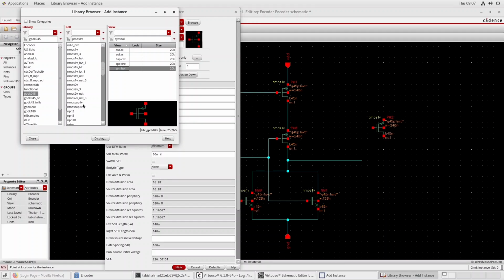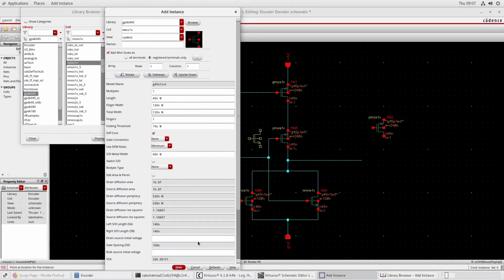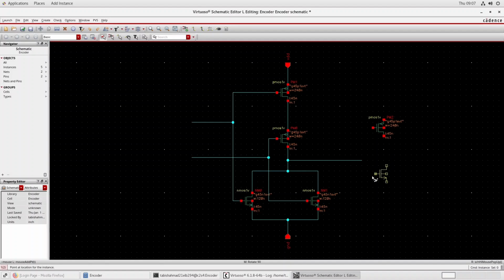In the priority encoder we know that we require three OR gates, one AND gate and one inverter. So to make an OR gate from a NOR gate, we need a NOT gate cascaded to the NOR gate. So that's what we are doing. We are connecting a NOT gate in front of this NOR gate. So the overall function will be an OR.